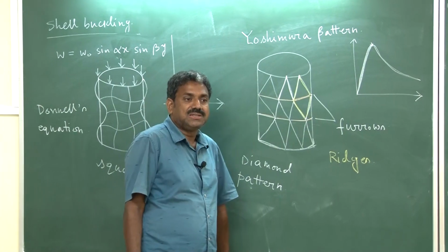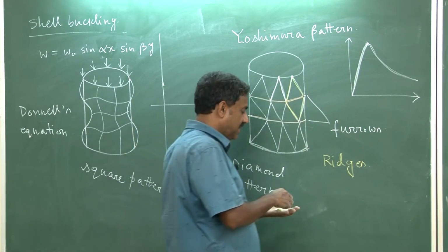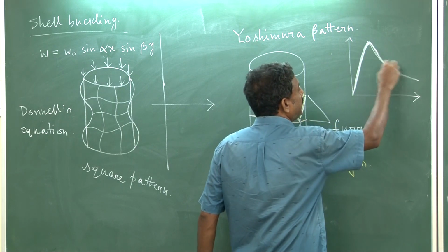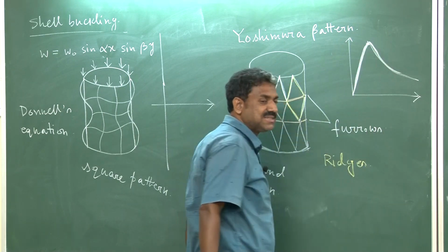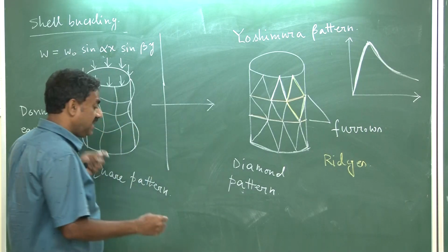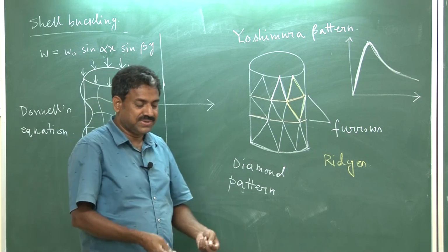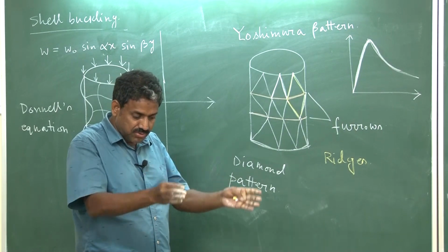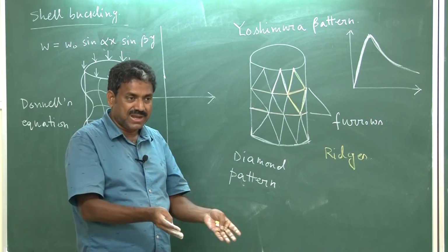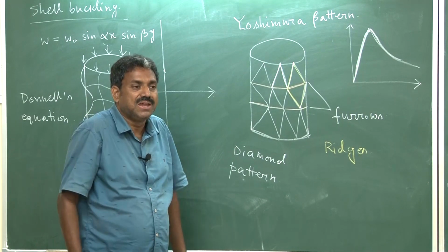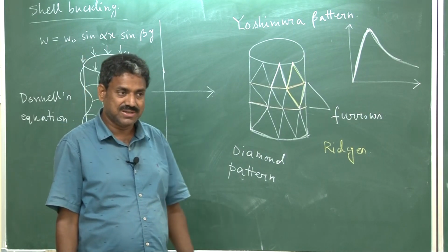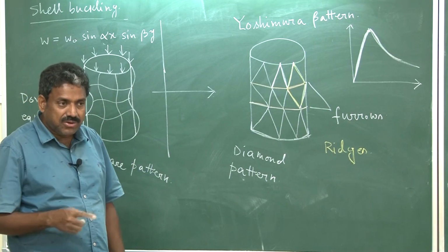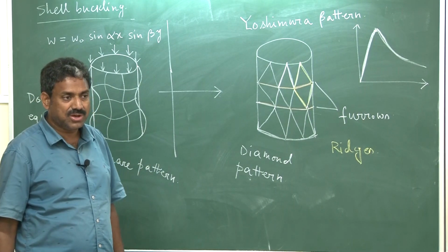All the strain energy. So, that is the reason why you see that first loading increases and then it decreases. Why is this increase happening? Because initially when you are pushing this cell, the cell is trying to deform out of plane, and through that deformation it is straining membrane strain energy, okay, out of plane deflection, but that is adding membrane strain energy, not bending.